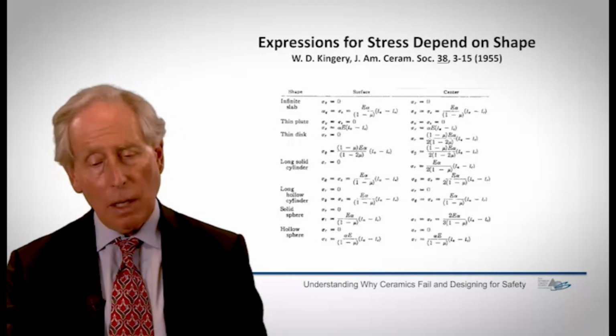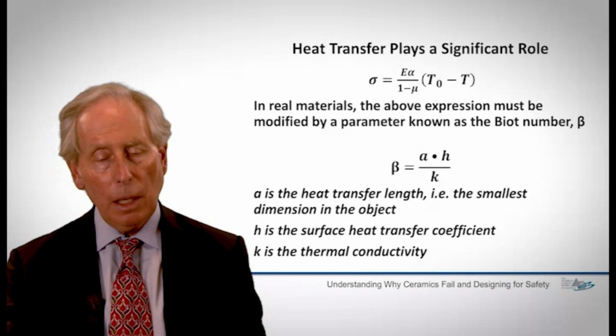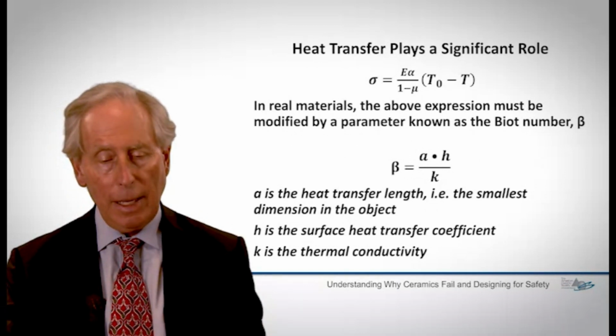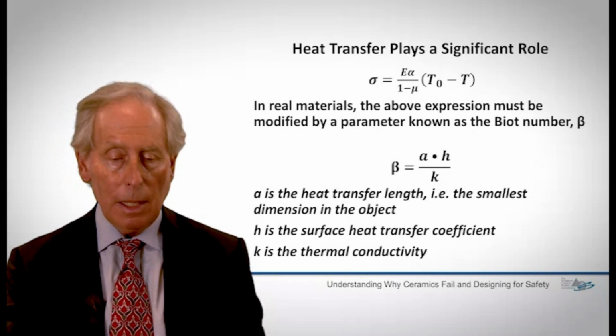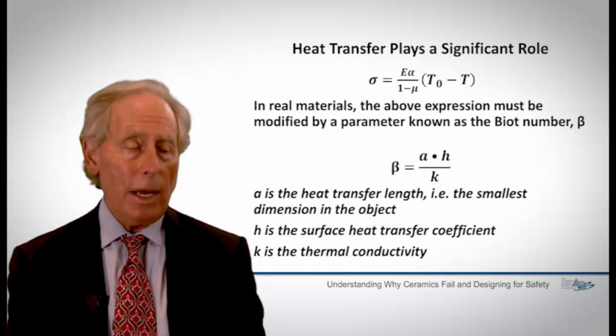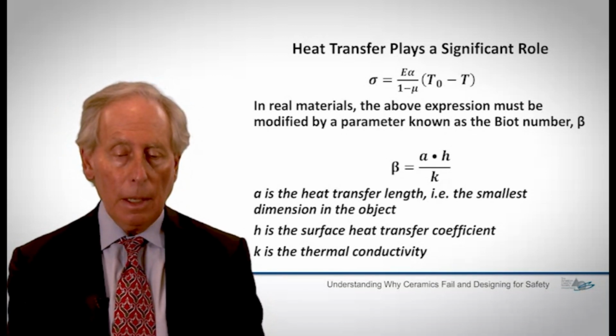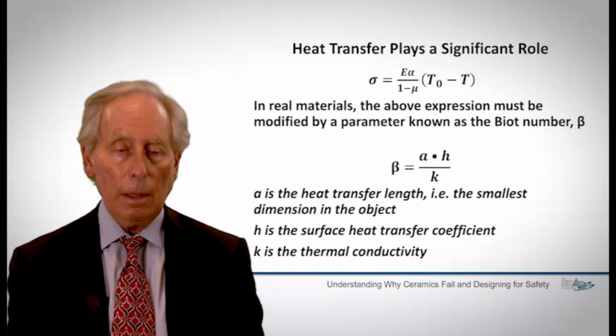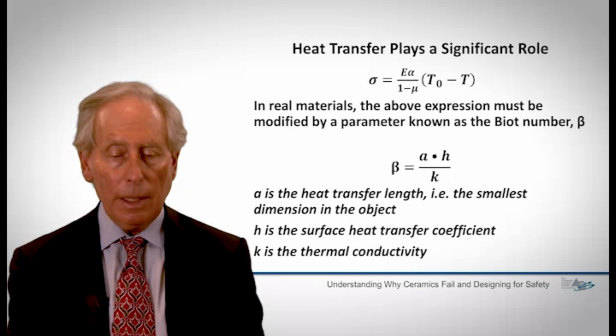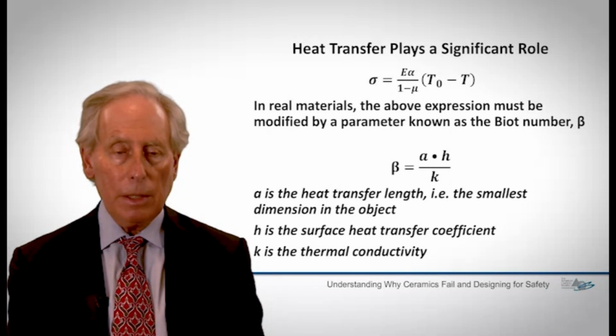But there's an additional complication which causes a real problem in understanding and measuring of thermal stresses, and that is the fact that the heat transfer coefficient between the part or the specimen that you're cooling from some high temperature to a low temperature has a significant effect on the stress development in the material.